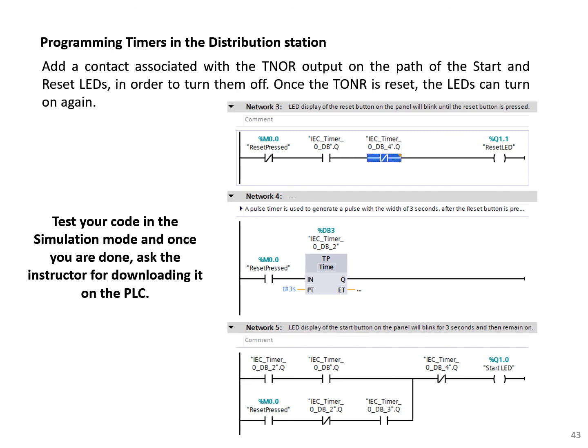Testing your code in the PLC sim could be a little bit problematic because you need to modify each variables or contacts one by one, specifically the real input devices, yes, for like switches. For the internal memory or outputs, you don't have to modify it because the program will take care of those variables.